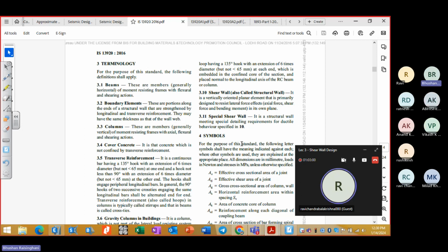So that plate also will bend in that direction, right? So moment has to get generated versus the shear that has to get generated. So your estimation for shear will not be correct. Okay, so it will show the forces, but the forces are pseudo forces, because it is a 2D element, you require a 3D element.